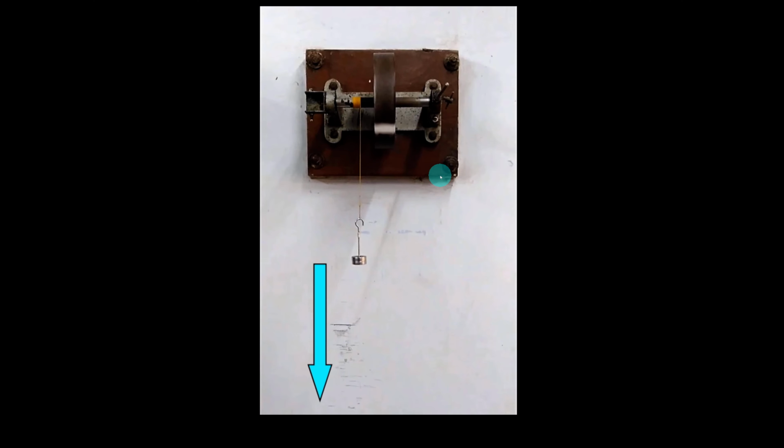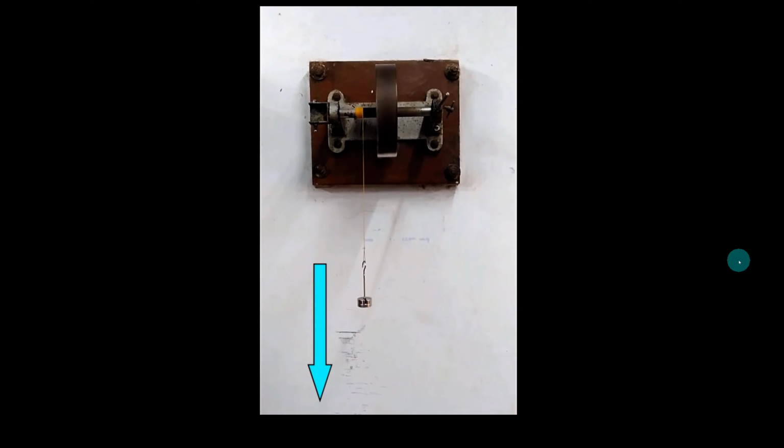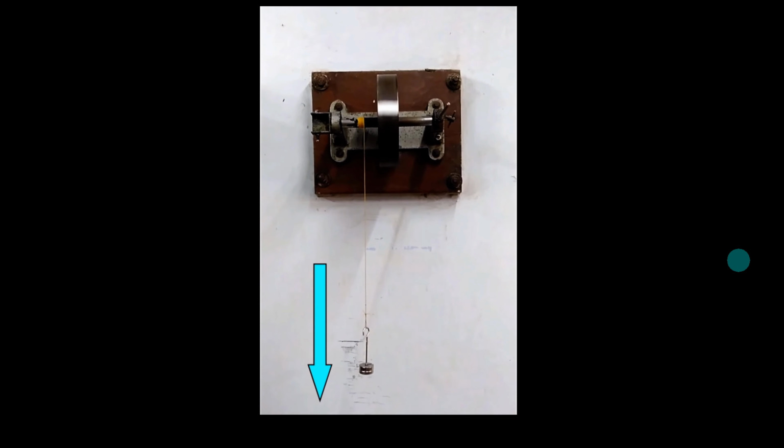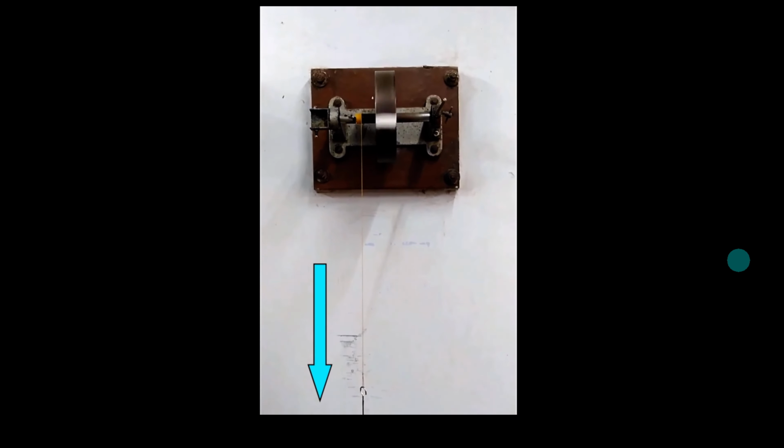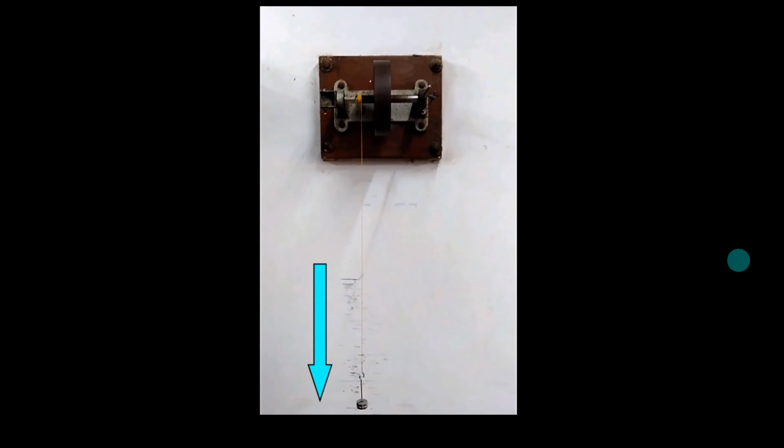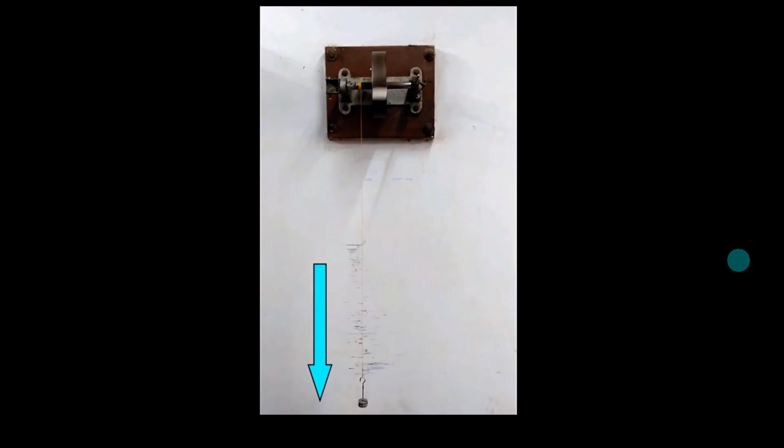Let the stop clock run, and you count how many turns it is making: 1, 2, 3, 4. It may be revolving for 120 times, because this will not stop easily. This rotation will keep on going, and your stop clock will be continuously running. You allow the stop clock to run until this flywheel comes to a stop. This will take some time. Once this particular wheel comes to an end, you immediately stop the stopwatch and note down the time shown by your clock.